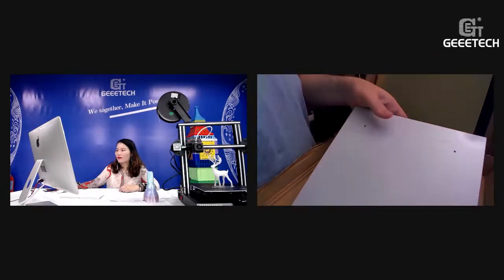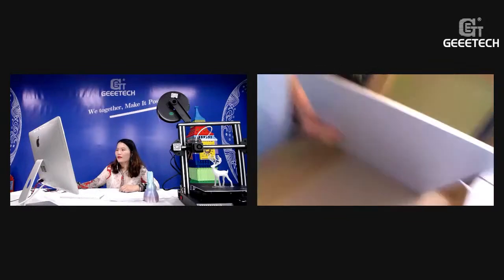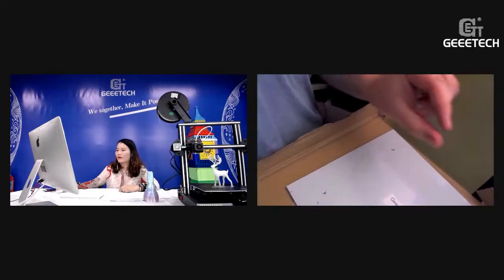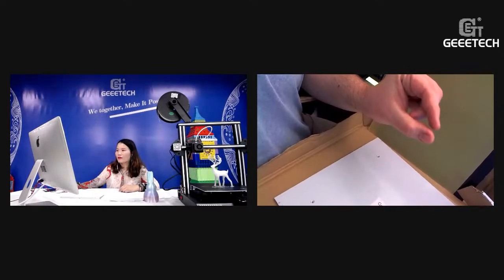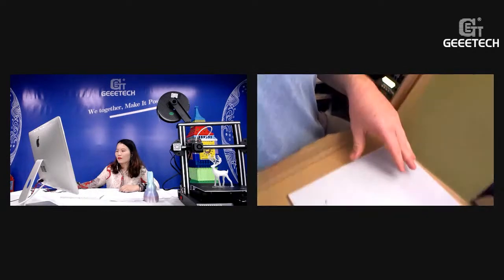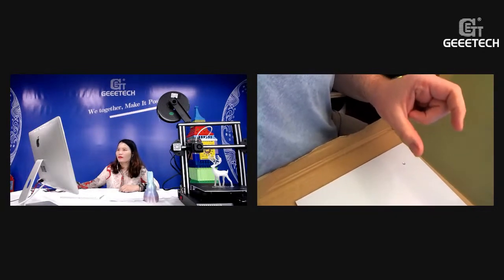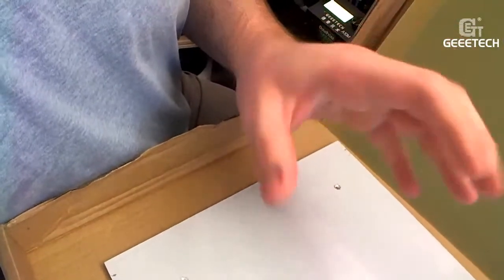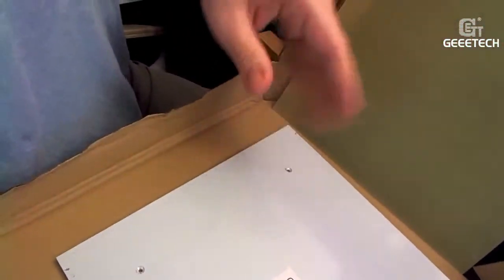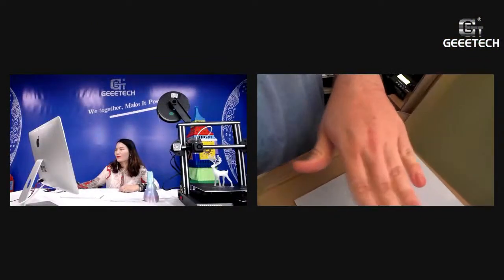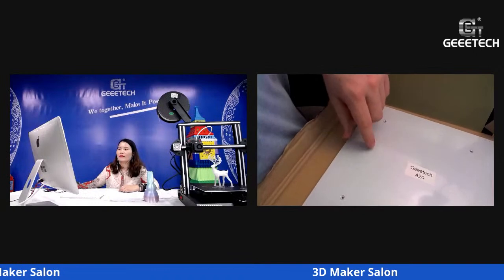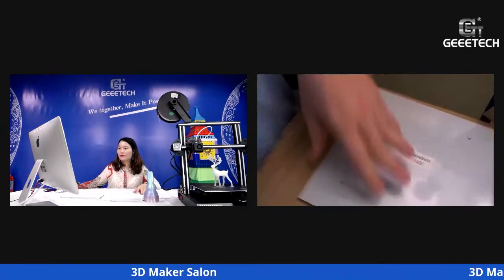And the biggest upgrade in this box is the aluminium sheet, because as some of the people may know, the glass and aluminium sandwich plates on the printers are too thin to have it well leveled, and because of temperature changes of the print bed, they expand differentially, and this will make the bed wobble a little. And as all of you know, a wobbly bed is not that good, because the printed parts will mainly not stick right or be too up or too down.